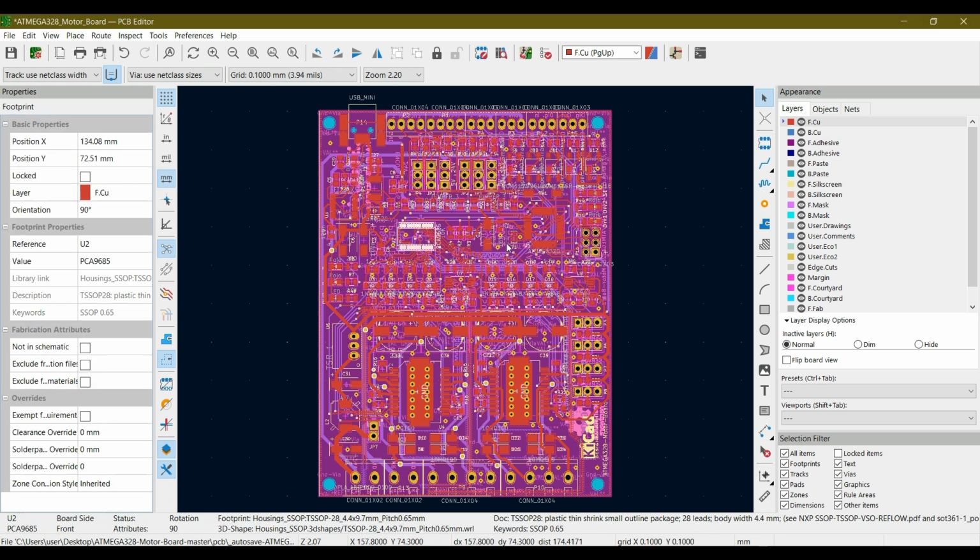So the file that will help the machine understand the position of the components on your PCB is called the component placement file. Component placement files are text files that list each component on the board along with its center position and orientation. These files are used for programming pick and place machines and may be required by your manufacturer if you are ordering a fully assembled PCB.